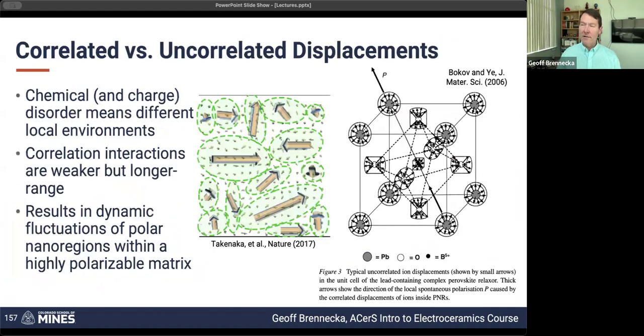If not, jumping again, I'll continue trying to explain what we're doing with the relaxers. Along the lines of your question, though, I think we talked a little bit about calcium doping of barium titanate when looking at MLCCs. So calcium is in the same column as barium, it's alkaline, but it's much smaller. So when you put calcium in for barium titanate, some of the calcium replaces barium, some of the calcium replaces the titanium.